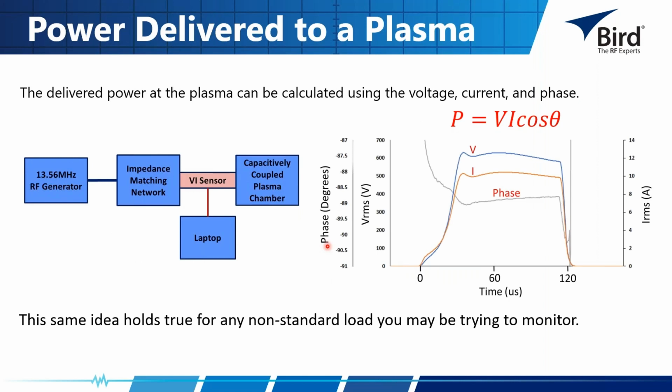If you're doing other things that are going to have variations in impedance, you can always use a vector network analyzer, taking into account voltage, current, and phase to accurately understand the impedance of a device. But really what we're talking about here is power measurements, especially of a dynamic load, which requires the power to actually be flowing through the system while you're taking a measurement.